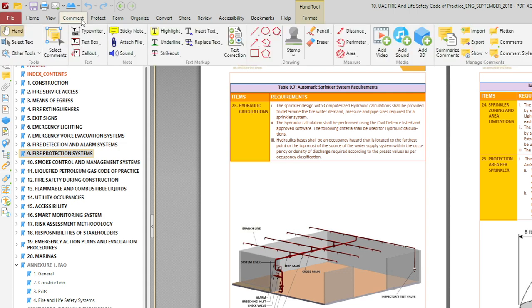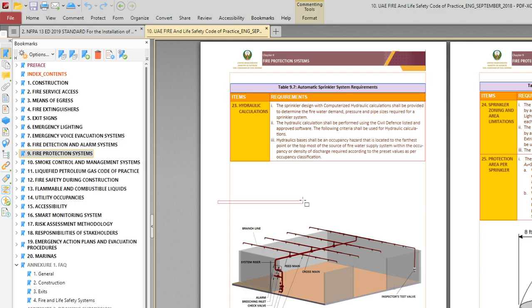So that means whenever you have a sprinkler line from the discharge of the pump, you can provide one riser, then you can provide one alarm check valve, and whenever you have a zone control valve, this zone control valve will cover either one floor, or one zone control valve can cover up to 4,831 square meter.